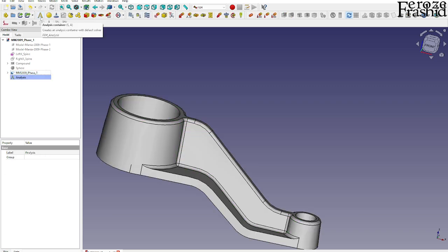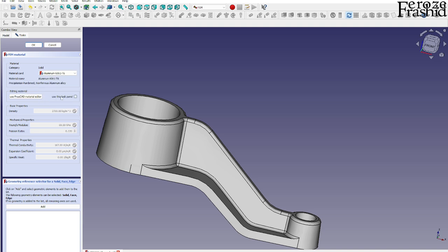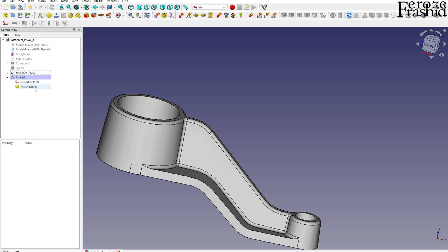steps. So first, bring an analysis container and put in a solver in that container, and then specify the material. And I think it says aluminum 6061-T6, so that's the one. Good, we have it. And I want to see if it has Young's modulus, Poisson's ratio, but it does not have the maximum allowable stress in this material. So we may have to do a quick Google search, because we'll have to find out the factor of safety. Anyway, Google is there to help us. Right, we need to fix